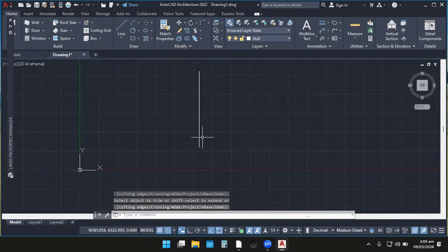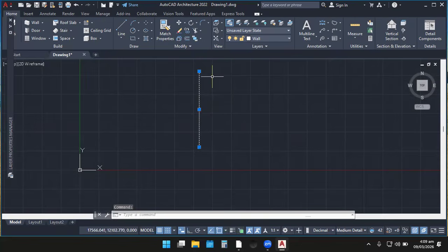Okay. So I want to offset this line the same dimension. So I'm just going to click this line like this. Then after clicking this line, I click on offset. This is offset. You see, now look at the command window. They say I should specify distance. So I come and click inside the command window to specify the distance. So I want to use, let's say, 12,000.